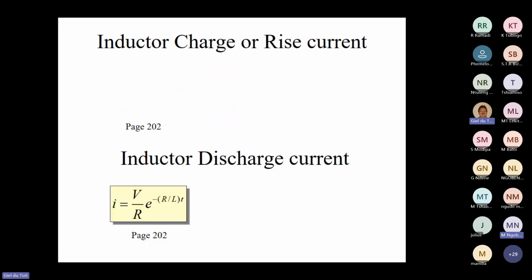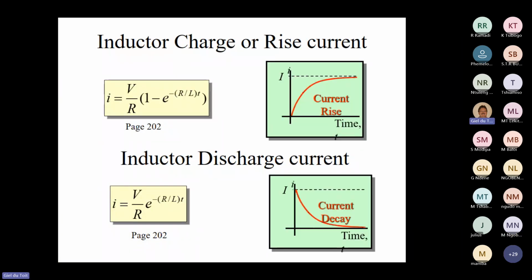So let me get to my formula again. So again, for the instantaneous current and the delay, that V over R will be basically the voltage that you had over the inductor at this point after charging it, say, to half the value, and then you're discharging it. So we won't use the final value here, this V over R. It is the value at the inductor after this time. We begin with that. Plug it into the formula, times e to the minus t over tau.